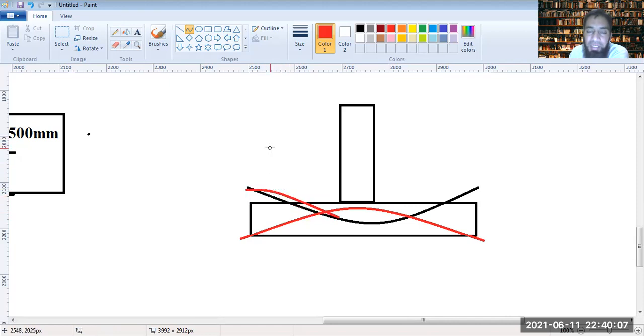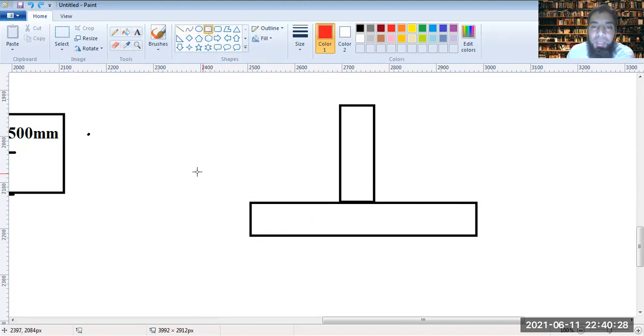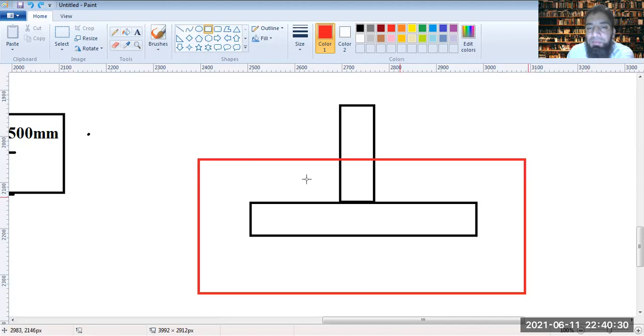The tension side would move towards the top. Is it so? Do you think this is how it behaves? If this is the case, what is the role of the soil beneath it? There is soil here that's holding on to this footing. It's exerting reactions onto this footing. It's not allowing it to bend. So it's offering the reaction to this footing.